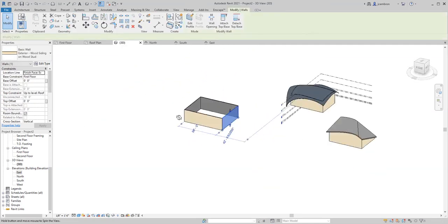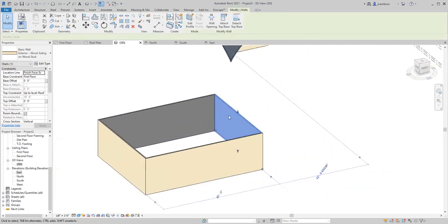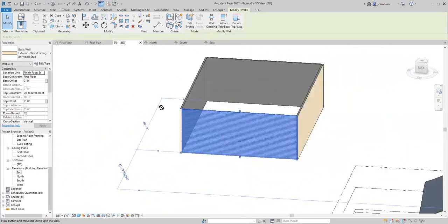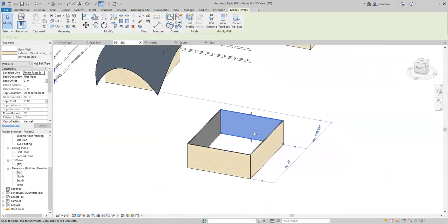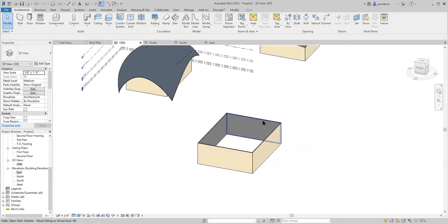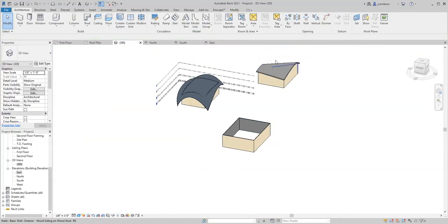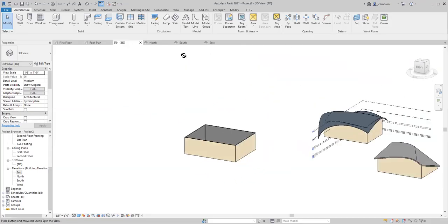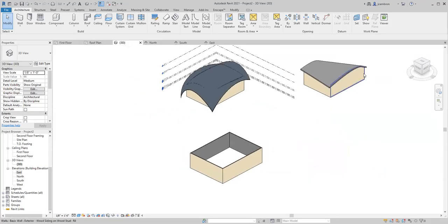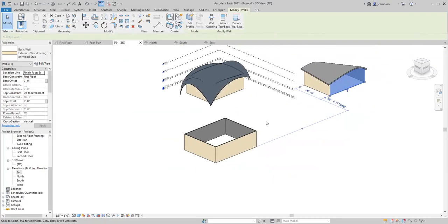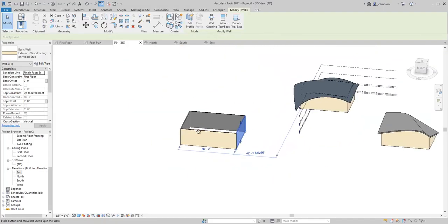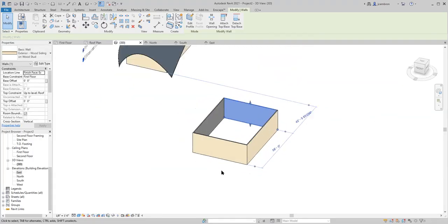And now I can actually orbit around that one object. It makes orbiting a bit easier. But then it becomes problematic if I'm trying to orbit something over here. So then I'd have to select an object over there, and now I'm orbiting around that one object. So let's go ahead and bring this back so we can orbit around this.